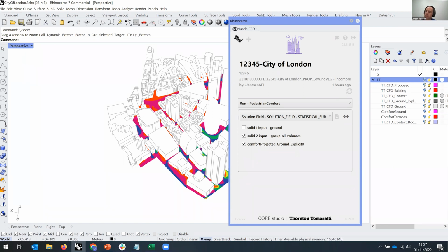I think definitely getting that data out in terms of points, or even post-processing now, perhaps putting in a mesh and a set of points, and from this result post-processing, would be very valuable, so that you can always change your points after the fact, because that's the one downside of the way SimScale runs their solver and only stores the results you preset. It might be useful to have that as a post-processing in the app as well, or through a Grasshopper component. Because now it's Rhino geometry, so now we can do Rhino interpolations and all that stuff relatively easy.